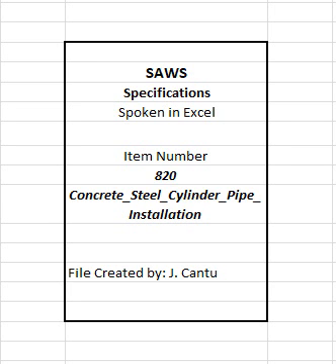C. Include physical and chemical property tests utilized, testing frequency and test records, and description of methods employed to assure compliance with AWWA C301 or AWWA C303 regarding wire surface temperature, type of thermometer, location of temperature measurement, frequency of temperature tests and test records. D. Approximate dates when wire will be manufactured for use in pipe.